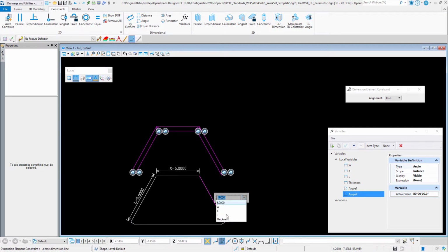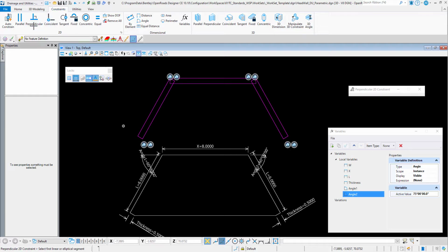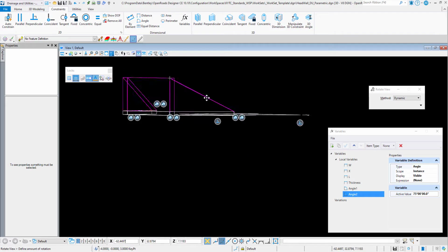Now this is a little bit different because this is the outside perimeter, which has this little lip. So I'm adding a thickness to that. And as I've tested things before, I know that if I change some things a little bit weird to different angles, sometimes that thickness that we had seen right there becomes no longer parallel or it goes out in space. So as I'm testing it, you'll see I'm going to want to choose a parallel or a perpendicular constraint along those two edges. And because I traced over the bottom and they're all planar, I can now also coincidentally tie that bottom shape to the bottom underneath that collar.